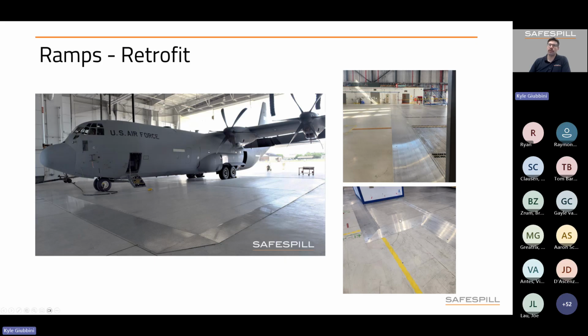In other areas where there's only light equipment or personnel moving onto and off of the floor, we're able to utilize a steeper ramp that has only a 1 to 12 slope, has about a 2-foot standoff from the footprint of the floor.